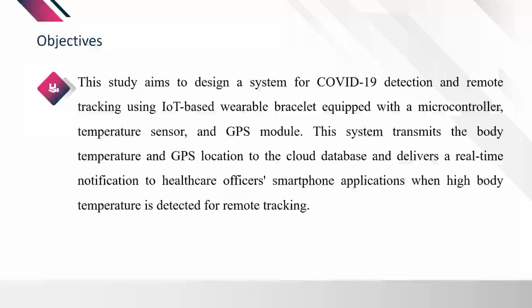The objective of our study is to design a system for COVID-19 detection and remote tracking using an IoT-based wearable bracelet equipped with a microcontroller, called Node MCU, with a temperature sensor and a GPS module. This system transmits the body temperature and GPS location to the cloud database and delivers a real-time notification to the health officer or system monitor, and to a smartphone application when the body temperature requires remote tracking.